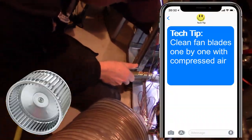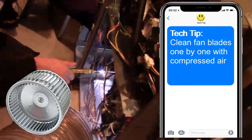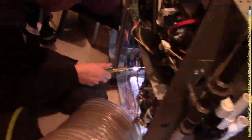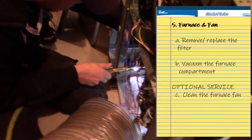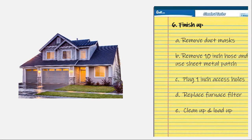Clean the fan blades one by one with the compressed air. Finishing up the furnace area, remove and replace the filter. Vacuum the furnace compartment. Clean the furnace fan. The final step is to clean up and pack up. Remove vent masks, remove 10-inch hose and use sheet metal patch. Plug 1-inch access holes, replace the furnace filter, or advise the homeowner to make the replacement.